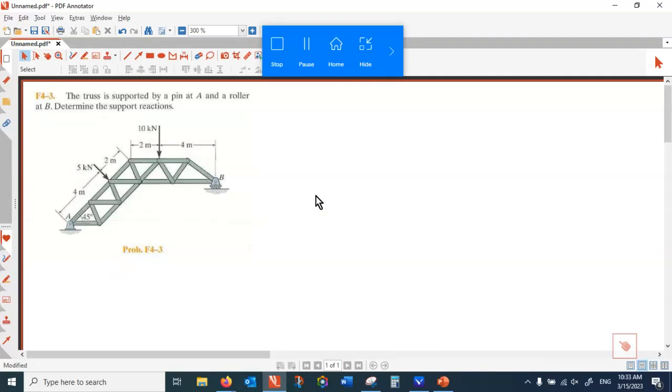So in this demonstration, we keep doing the equilibrium of the structures under different two-dimensional and three-dimensional loading. And like I said, the key prerequisite is that you need to know the different types of supports, because in studying the structure and making the free body diagram, the first thing we do is separate either the entire structure or a part of the structure from the universe, and then we study that within the frame of a free body diagram.